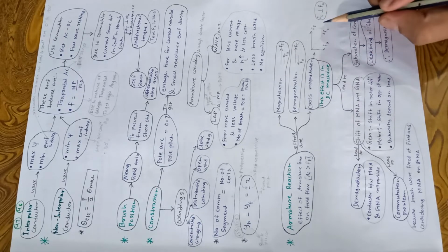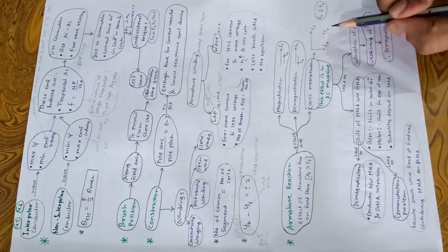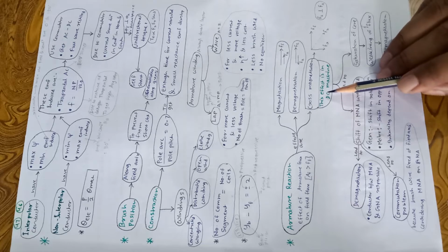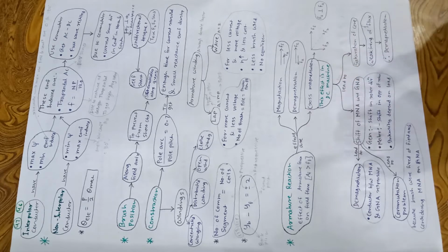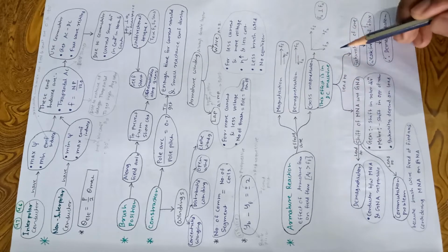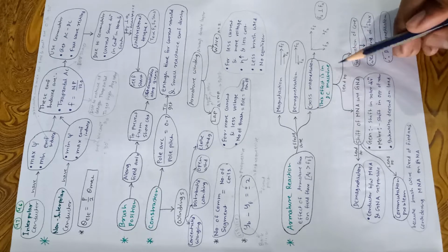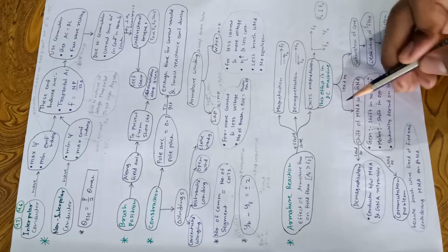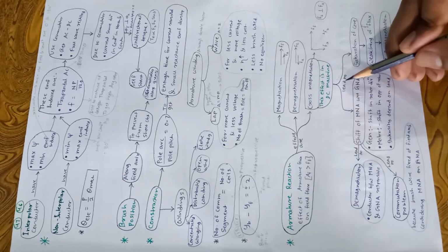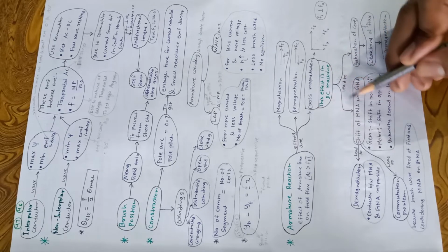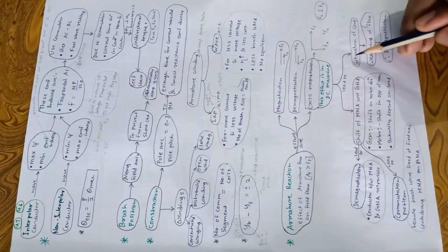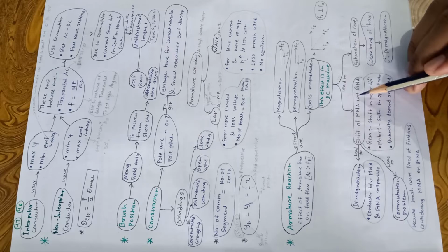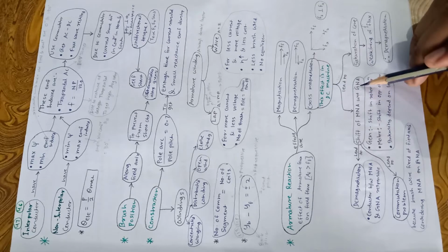We know that field flux and armature flux are perpendicular to each other, so there will be cross magnetization only, and this effect is seen in DC machine only, okay. So we have these two perpendicular, so due to this cross magnetization, see what are the things we have. Okay, we have saturation of core, and MNA gets shifted with respect to GNA.